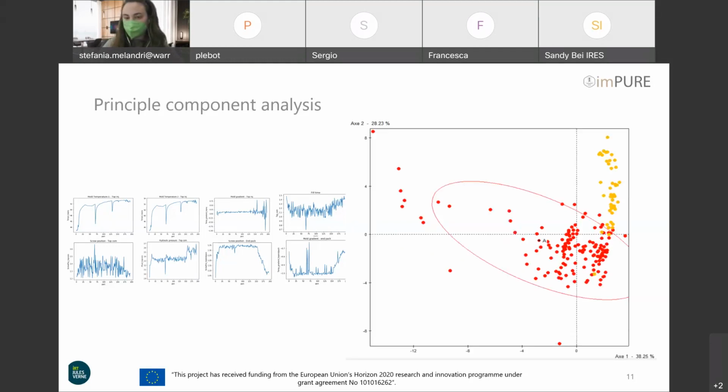Now, the principal component analysis from these 50 parameters gives this type of result. You can see the projection of each point. One point is one part. On the eigen axis here, axis 1 versus axis 2. Parts for which a process defect has been deliberately introduced can be detected quickly. It's the orange points there. In one single screen, potential anomalies can be detected.